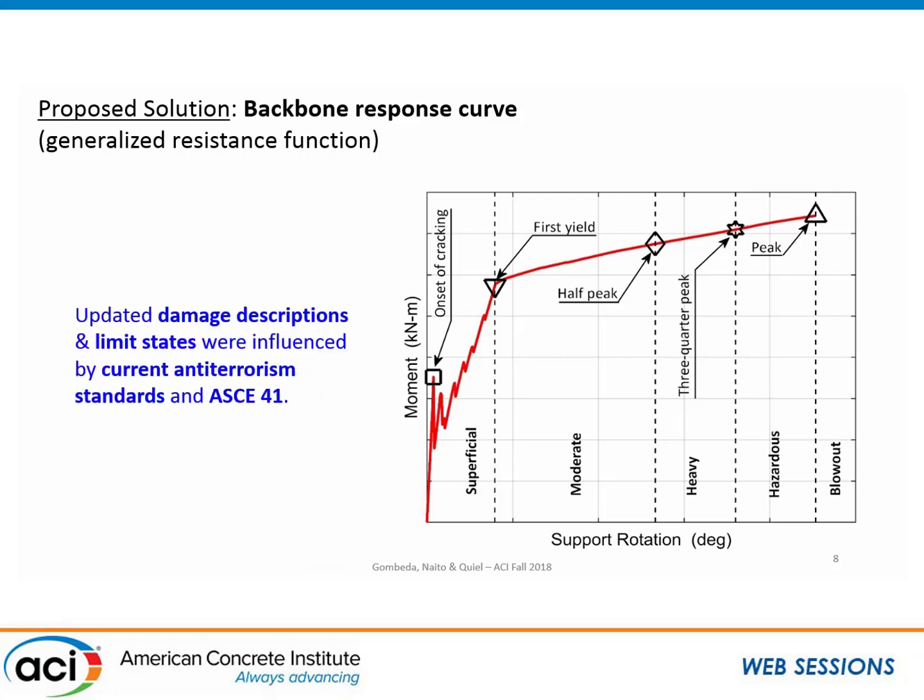And the damage definitions themselves are also a little bit influenced by ASCE 41. We've looked at seismic components and asked, what are the criteria that they have there? What damage is associated with that? And we've tried to keep that in mind while we develop these things.